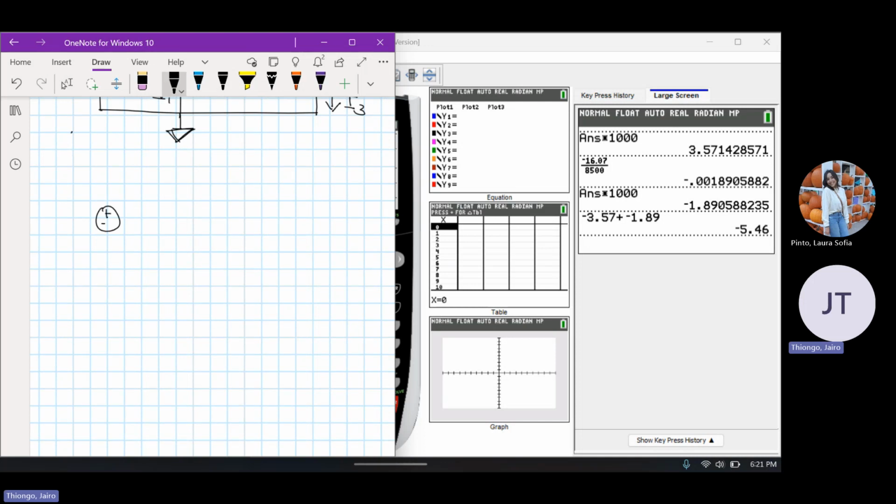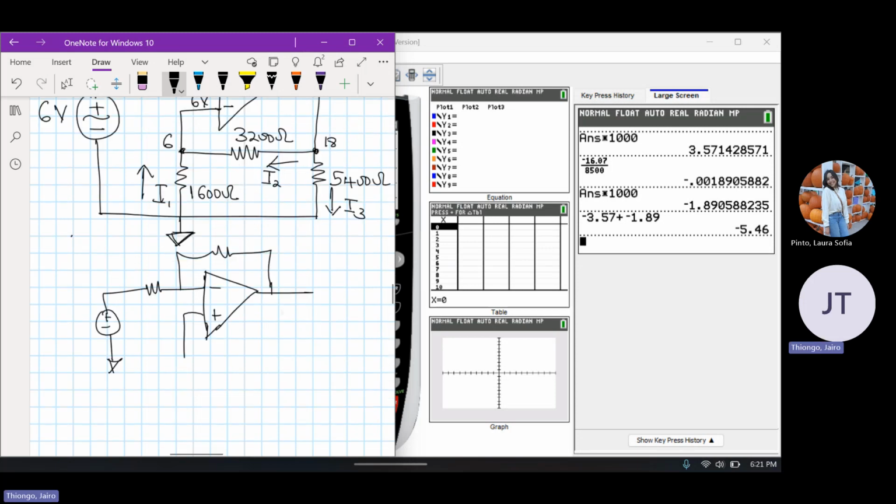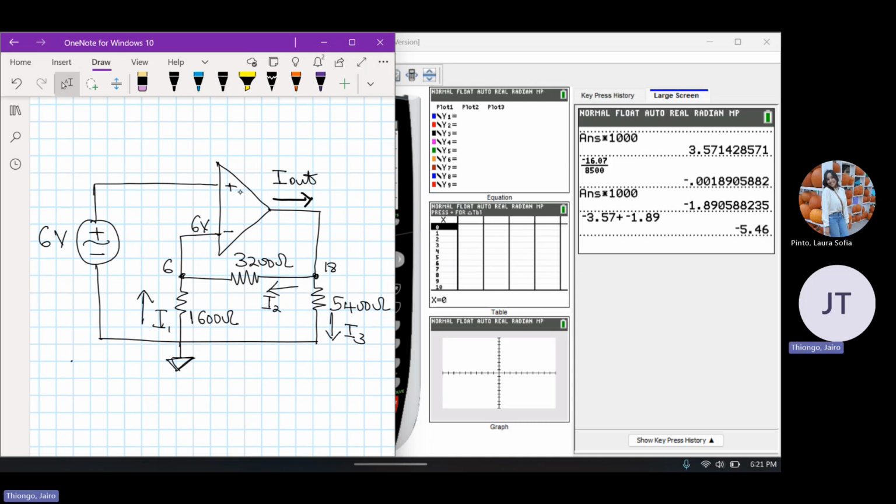have the voltage source, minus input, minus plus, and you have a resistor here. My drawing's not that good, but it's just for demonstration purposes. So this is a typical op-amp configuration. As you can see, most op-amps you have seen before up until this point have been connected to the negative terminal. Unfortunately, in this question, the Vin is not connected to the negative terminal. It's connected to the positive one.